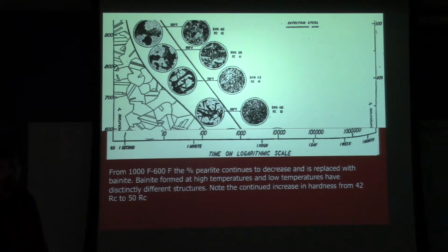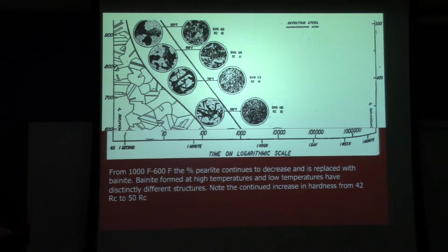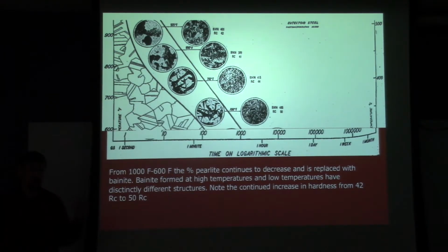So we have in this particular alloy, which is plain carbon steel, at 0.8% carbon, 1 second to get it from its austenitizing temperature past the lower temperature. 1050 was the nose of the curve for this alloy. So yeah, that's extremely important. If you're trying to make something that's free of pearlite in this particular composition, you have to cool it past at least 1050 in 1 second. Which means your specimens have to be very small, or you have to have some very large cooling capacity, or some combination thereof.